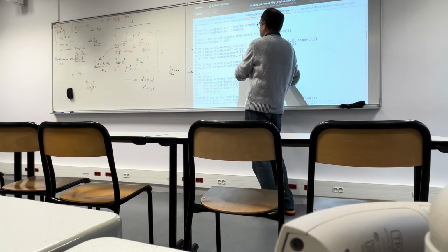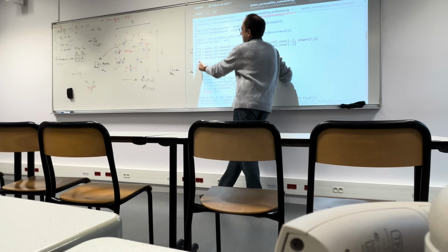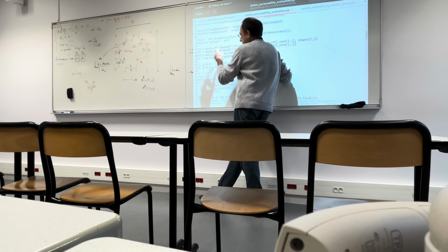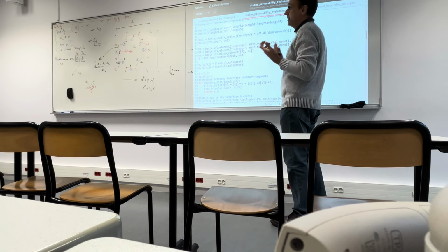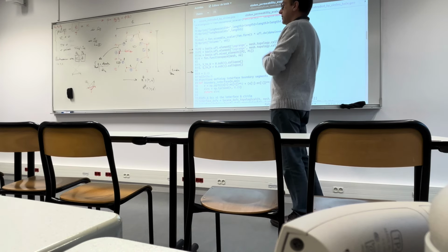P2 for the velocity, P1 for the pressure, and the space W is the function space which is attached to the mesh and based on these polynomials. So this W is the space of functions where we are looking for the solution of the problem, in terms of a kind of Cartesian product between the space for velocity and the space for pressure.